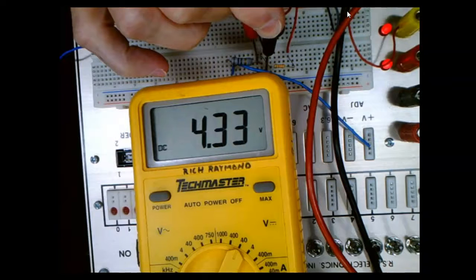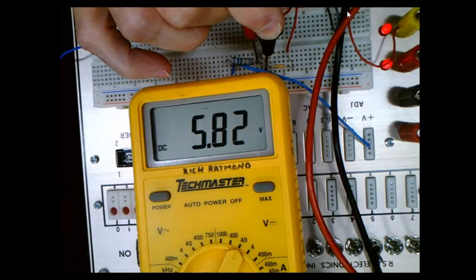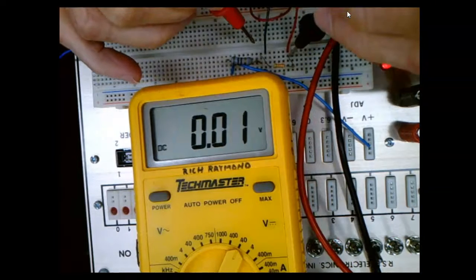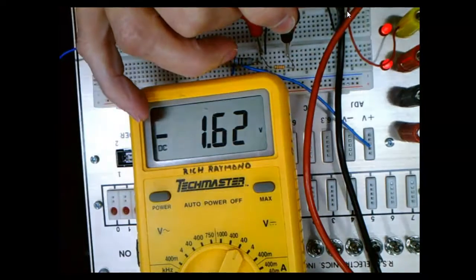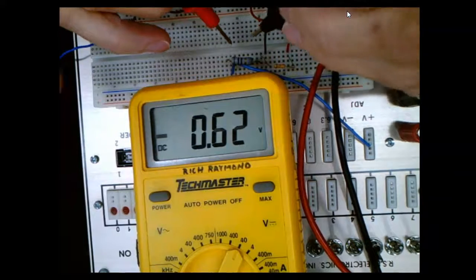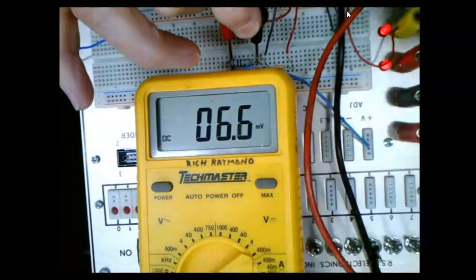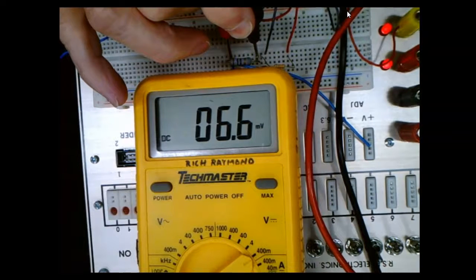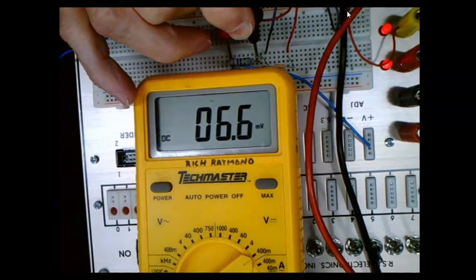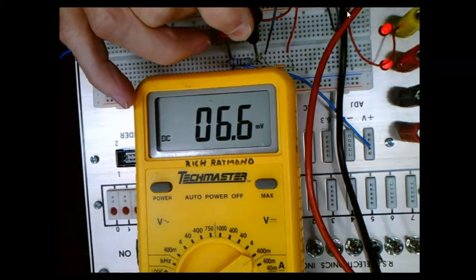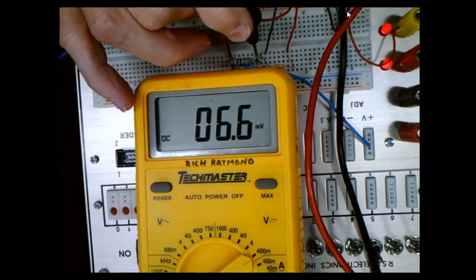So here comes 6 volts. We should see this vary just slightly. So there's 6 volts, close enough. Double check my base current. Still should be 1.6. See, the base current is saying the same, right? That's really good. Okay, so this is VR2. So now it's measuring about 7 millivolts. Excuse me, no, we're on 6. We're not to 8 yet. We're just now on 6. So VR2 is 6.6 millivolts or 7, so about 700 microamps, right? I mean, I'm sorry, 70 microamps. I keep going one over. Are we okay?